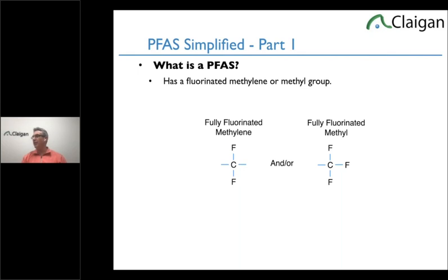If we strictly make articles that utilize polymer types, would the incidental presence of restricted forms make these products restricted? Yes. So if you use PTFE and it has PFOA, it's restricted in Europe, even though you didn't mean to have it. The restriction doesn't care if it's intentional or unintentional. The reporting cares if it's intentional.